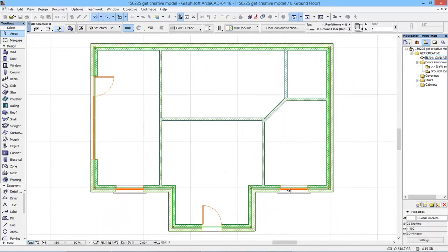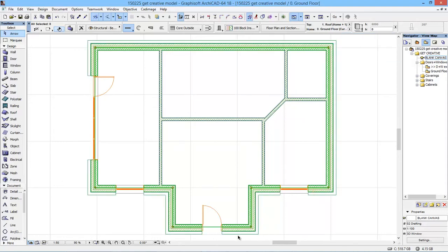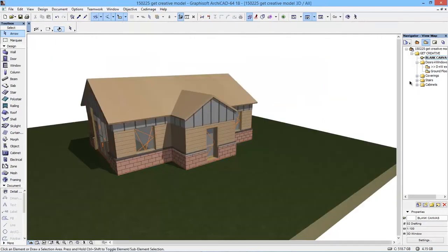When I do that, the screen zooms in and I can choose to offset this inside or outside. I'm just going to snap it to the outside of the wall. You'll see it does its little calculation and the new trim actually appears. So in terms of 2D and in terms of pure modelling, you have a couple of choices here. Some people just use this as a visual thing, so they're not too concerned about the overall thicknesses. If you wanted to do this absolutely properly, then what you should probably be looking at doing is not modelling the outer skin of the brick wall, so that when you then put the covering on, you're getting the correct thicknesses, etc. But that's far too technical. Let's just see what it looks like.